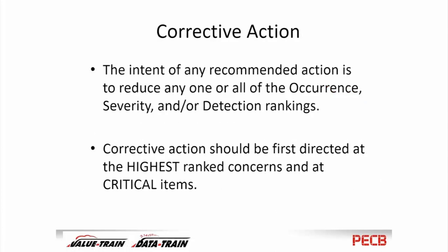And that by itself isn't going to be extremely useful. We're going to compare that risk number to risk numbers for other things in order to decide what to fix. And so we're going to be looking at this for many things, and we're going to look at many things that could be dealt with. And the RPN value helps us to rank those so we know which ones to work on. And you should work on the ones that have the highest RPN values first.